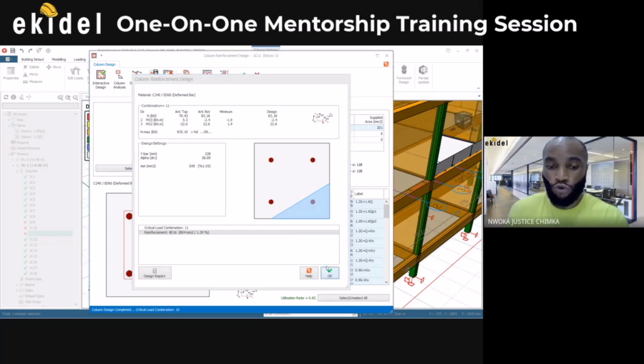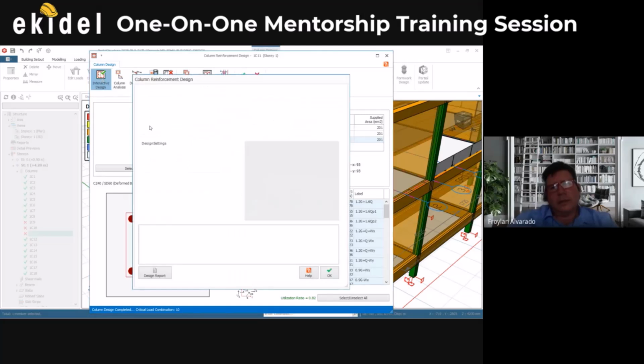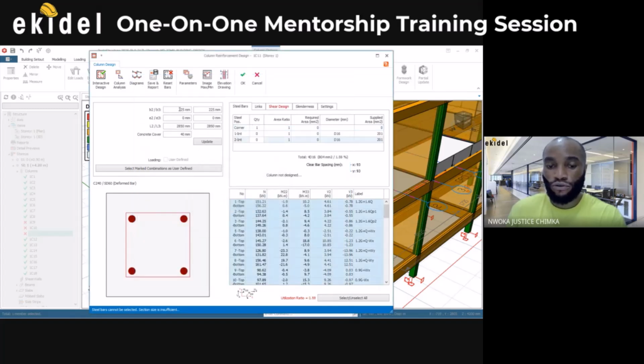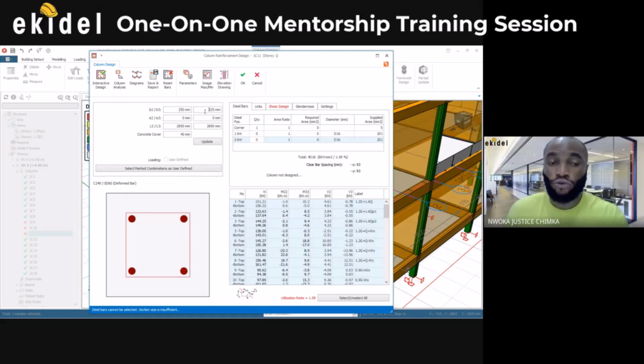For example, when it was 225 before, let's see that again, 225 by 225, and then update. You can see here it is saying warning. You won't see reinforcement. What you'll be seeing is the warning: steel bar cannot be selected, section size is insufficient. You understand? So I'll come back here and say okay, and then increase the section. Right? Because of the ratio, no? Still the ratio, yes, exactly.